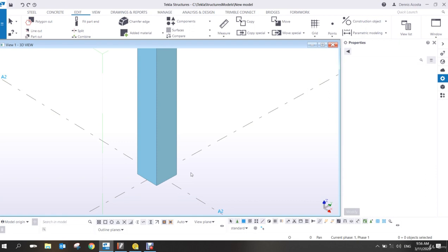All right. Now, how are we going to use the fitting? So the fitting must be used here. This one is the fitting. You can try to use the fitting and the line cut here. So check which one is really useful for this grout tube, the fitting or the line cut. Now I want you to use the steel here.